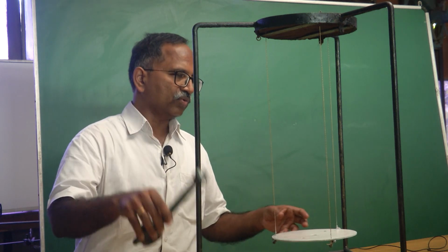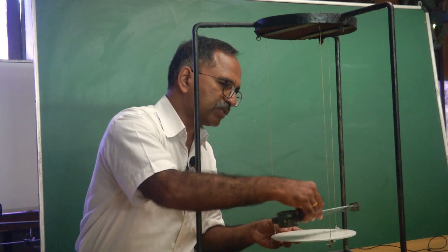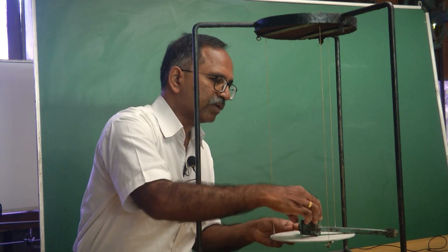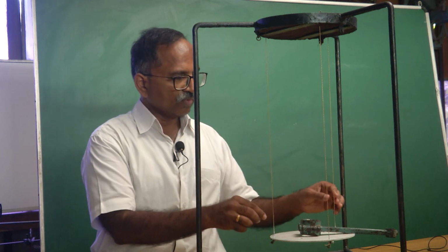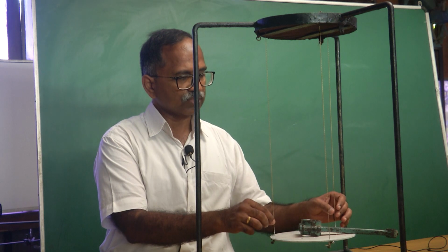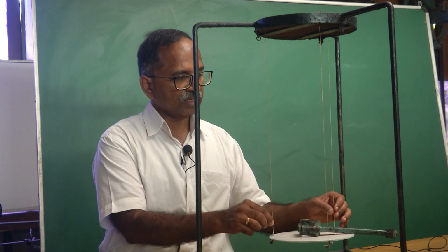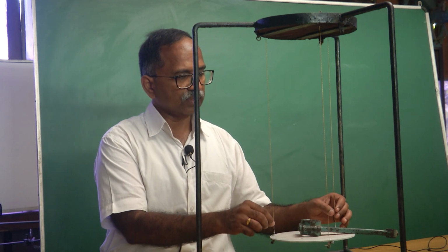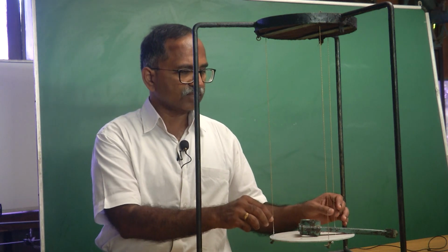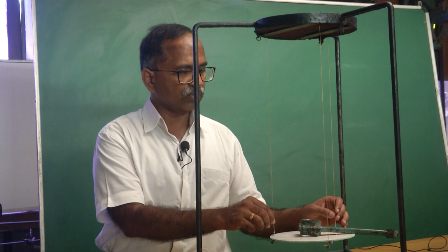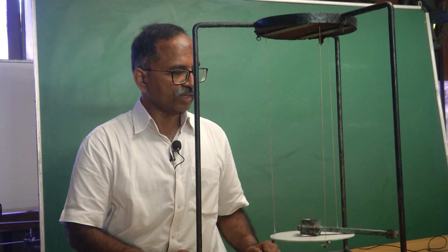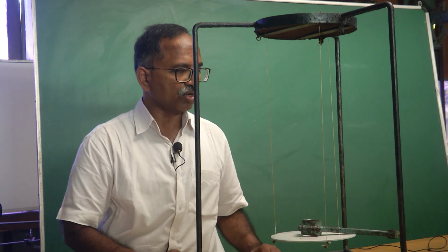Okay. So, I shall just place this connecting rod with its axis aligned to that of the plate, and we shall try and record the oscillatory motion and therefore, the period of oscillation. Okay. So, as we all know, for the derivation of the governing equation and the expression for natural frequency, the underlying assumption is small amplitude of oscillation, and therefore, it is imperative that practically as well we give a very small angular displacement, so that the oscillations are with small amplitude.